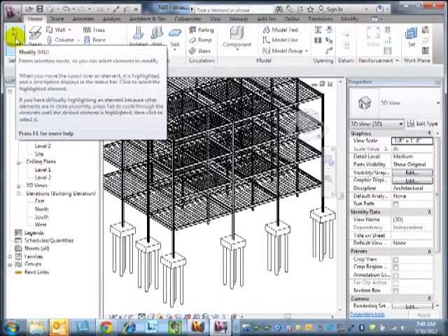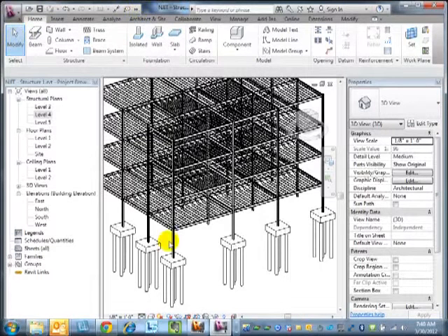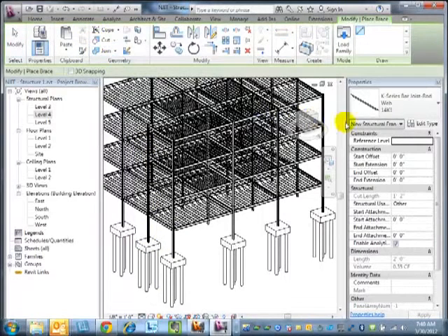Okay, so that's really the essence of a lot of the structural modeling. Most systems work out in this beam system, floor plates, that kind of system. We can also put in diagonal bracing, shear walls, things like that that are ultimately part of the system too. Bracing, there's an option of brace over there. Do you want to see brace? Brace looks like this. Braces are really just diagonal elements.